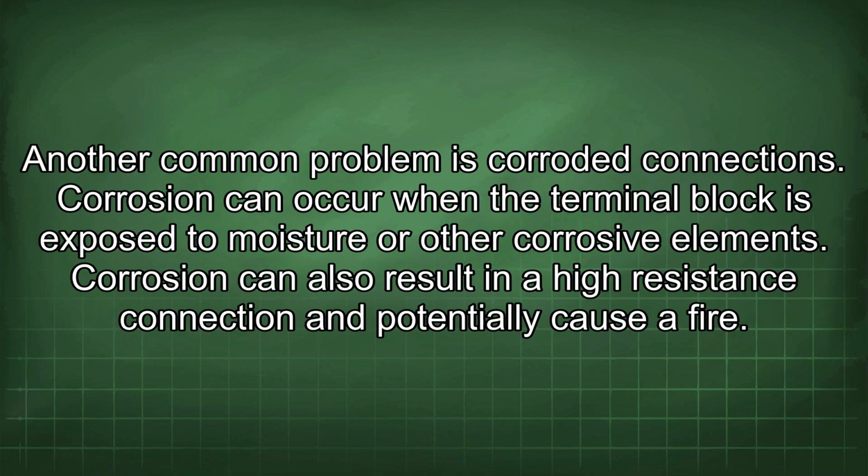Another common problem is corroded connections. Corrosion can occur when the terminal block is exposed to moisture or other corrosive elements. Corrosion can also result in a high-resistance connection and potentially cause a fire.